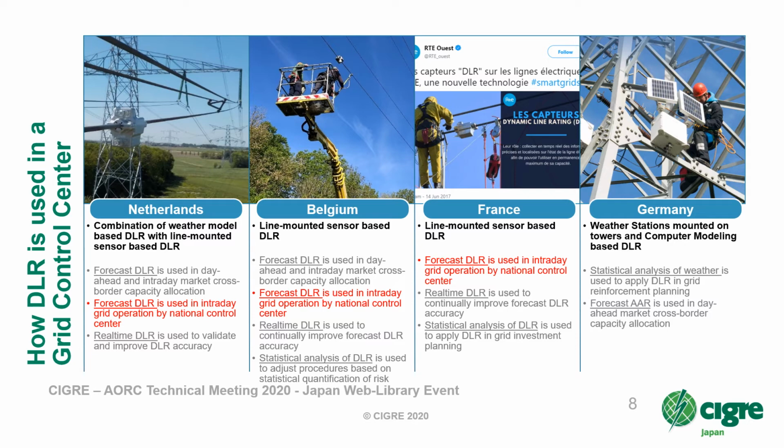So-called intraday operational decisions are largely made on the expected power flows resulting from forecast demand and forecast generation, including renewables. Some hours ahead of real time, power flow simulations are made based on this forecast information, including forecast dynamic line rating, and the operation of grid equipment like substation switching, transformer tapping, and HVDC terminal control are planned.